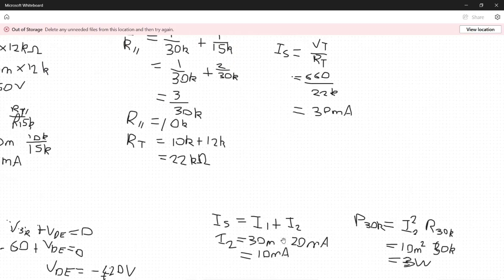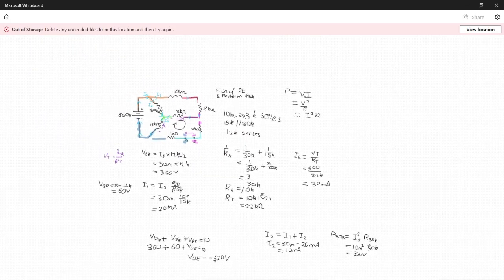And just like that, we've ended up solving the circuit by breaking it up. My advice when you're trying to actually solve circuits is follow a pattern. First, you're going to look at the circuit and then highlight all the nodes, all the branches, and break your circuit up into color so you can understand what's going on without needing to redraw.